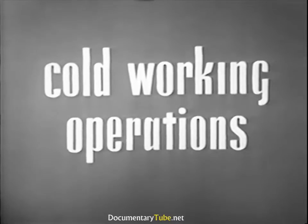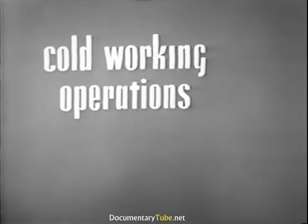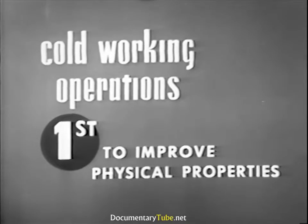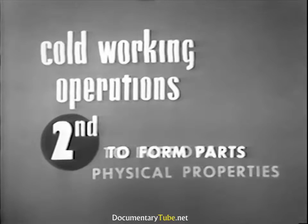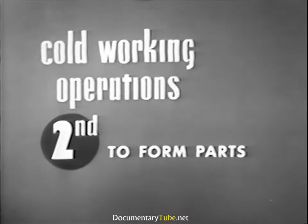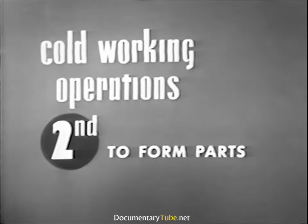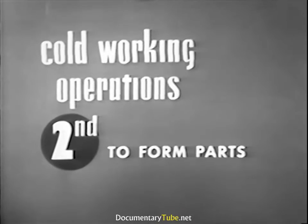Cold working or strain hardening operations may be undertaken for two purposes. First, to improve the physical properties of an alloy. Cold rolling and stretching processes are generally employed. The second purpose of cold working is to form parts from alloys with strain hardening resulting from the operation. This involves such processes as bending, hammering, hydropress forming, stretch forming, drop hammering, and deep drawing.